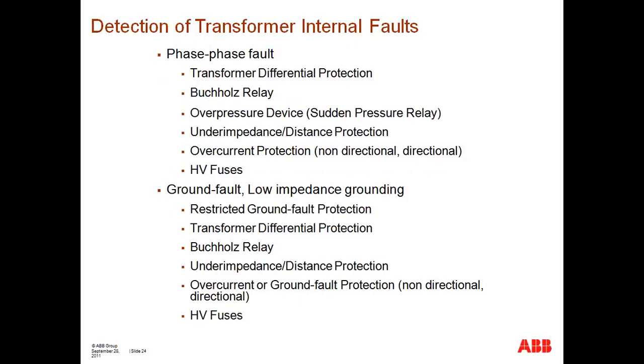A Buchholz relay is a mechanical device. Usually when faults occur, there's a breakdown of the oil inside of the transformer, and that breakdown results in gases being released. This device is essentially a floater type: when this breakdown of oil occurs and gas is released, that gas is going to come up to the surface of the level of oil.